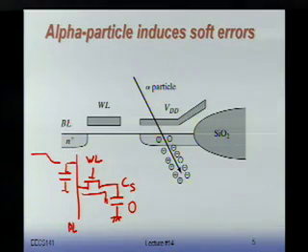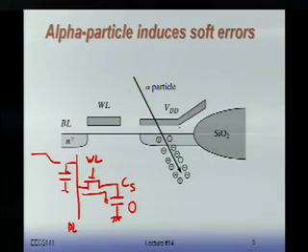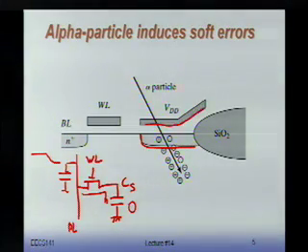You have the bit line, which could be metal, diffusion, and things like that. The word line is polysilicon. That's our transistor right here. And here you have your capacitor. I just showed an example of a capacitor that's implemented in diffusion, but you could do other things as well. Actually, it's typically not done that way. It's typically done a lot more complex than this. But bottom line is that I have here somewhere a capacitor with some charge on it.